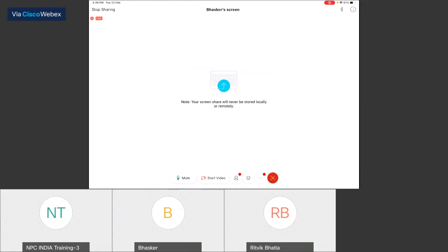You have to put this RC circuitry to see that the power factor comes up to 0.99. Don't go above the leading power factor, and that way you can save. The RC circuits are available so as not to go beyond that. As we are using KVAR capacitors for getting a good power factor, similarly, for not going into leading, RC circuits are also available.